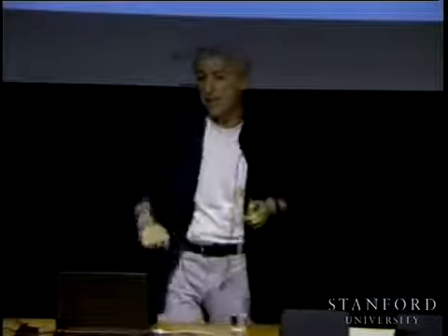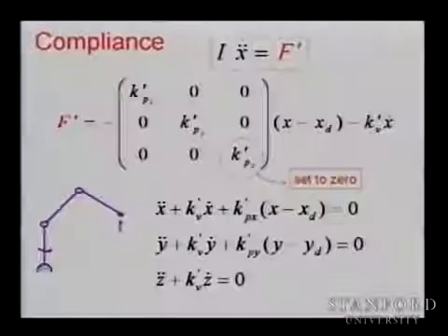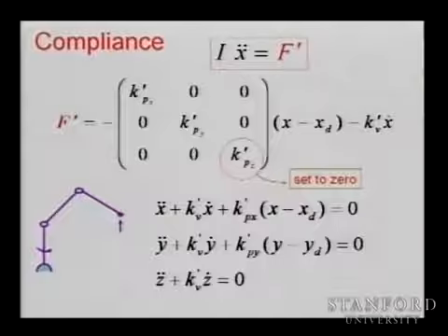But actually what we want to do is not only to create a compliance, we want to control the force, the contact force. So if I'm pushing the robot, I would like it to maintain 0 force. So when it feels any force, it moves away, which means we need feedback. We need a force sensor. And this is really the requirement in order to interact with the environment. Most of the time, you want to apply a specific force on the environment, and that requires control of forces. Here we just removed the position control from 1 degree of freedom, one direction.